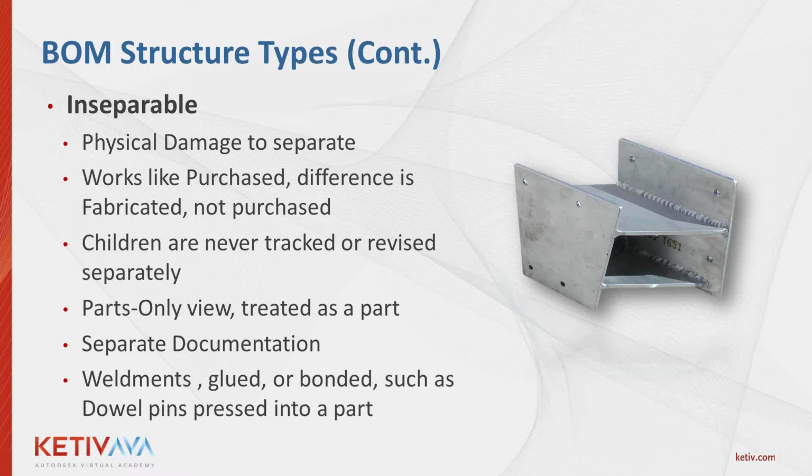And so if there was going to be a change, we wouldn't rev up just one of the components, like let's say the panel on the left-hand side. We'd technically do the whole assembly, really. So these are things that would be considered inseparable. They're basically an assembly that would be together, and you want it to show up as one line item only. And then you can open up the welded assembly and take a look at it in there and see its breakdown separately.